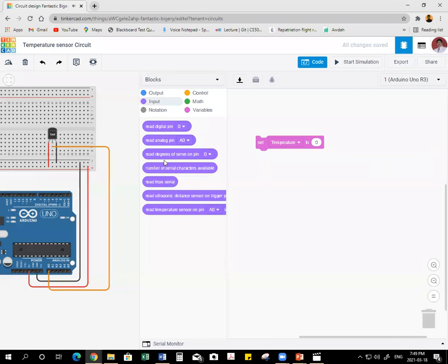read temperature directly. We have read analog pin we can have, that is by default block is there, no problem. Simple, I don't want to go because in future that may not be required. That is very simple. Directly it will read in temperature in degrees. But I want to show how to map, how to differentiate different ways. So I am reading temperature with read analog pin A0. Okay. And we are equating to the temperature.